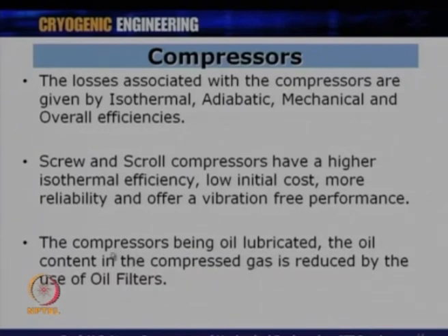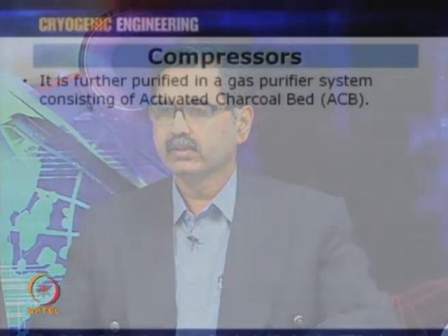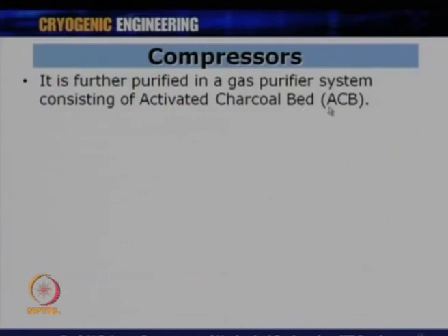As you know, cryocoolers, cryogenic heat exchangers or liquefiers do not like oil because oil will get frozen, and therefore, all the gas which is coming out of this compressor should be free of oil, and therefore, oil filters are a must. This is a very important requirement that this gas has to be stripped of the oil, and only oil free gas should go to the low temperature area. It is further purified in a gas purifier system consisting of an activated charcoal bed, so that all the moisture etc. is removed from this gas, and therefore only dry gas without moisture, without oil should go to the heat exchangers and the expanders.